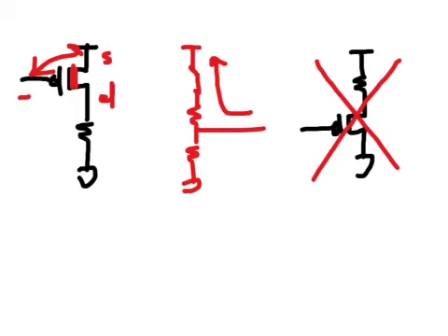Notice another thing. When, in this simple single transistor configuration, the PMOS or NMOS is engaged, when the channel is present, there is current continuously flowing in the device, that is dissipation of power, while the MOSFET holds a steady state.